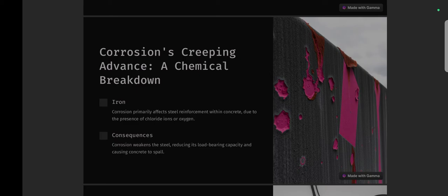This can compromise the integrity of concrete structures, especially in roads, pavements, and buildings exposed to moisture. To prevent this, use low alkali cement or non-reactive aggregates and ensure proper mix design. Additionally, controlling the moisture content can reduce alkali silica reaction risk.